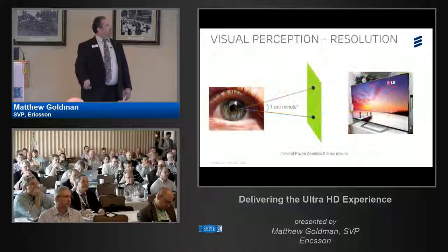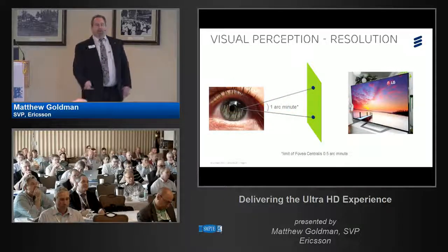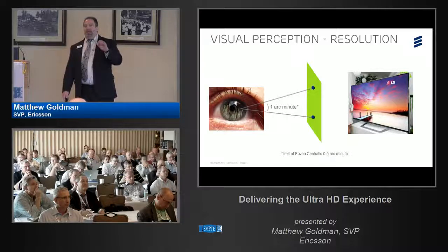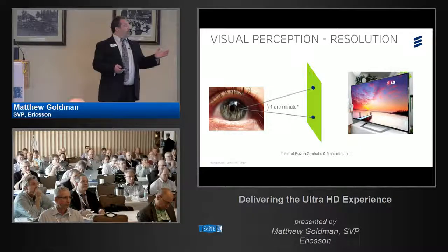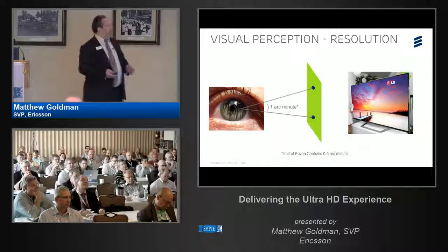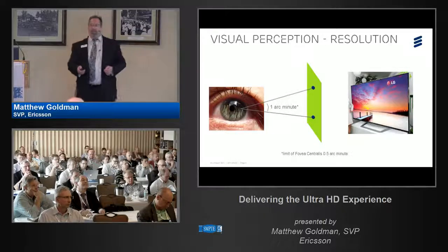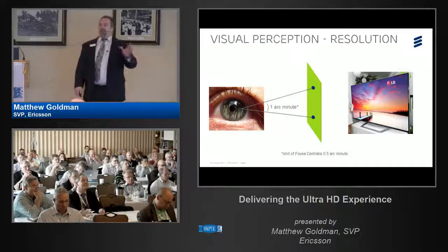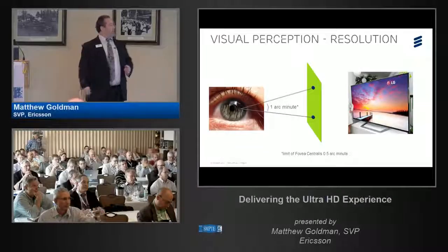Excellent. Okay, so it's important to understand that the human eye can only resolve so much resolution. Anything that is a higher resolution than that, your eye just can't see it, okay? And it's roughly, for most people, somewhere around 1 arc minute. If you really want to get more technical about it, it's about half of an arc minute for many people, but it's about 1 arc minute. That's what you can resolve. So because of this, it does matter how far away from a screen you're viewing something based on its resolution,